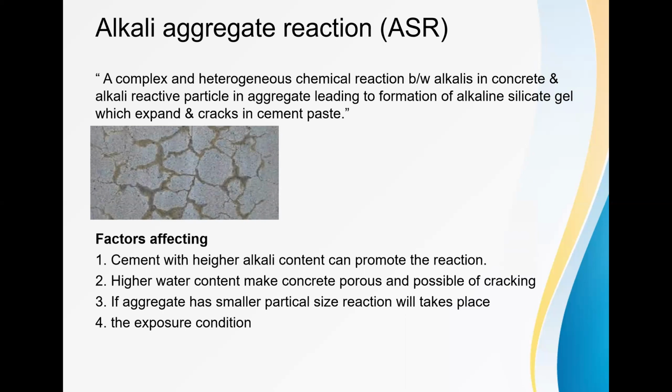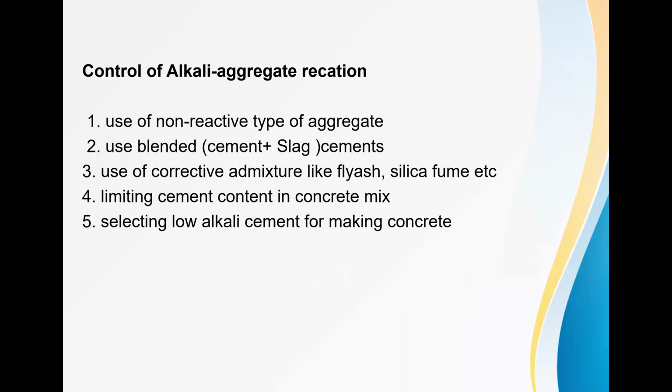Then what are the factors which are going to affect the alkali aggregate reaction? Cement with a higher alkali content can promote the reaction. Second, a higher water content makes concrete very porous and there is a possibility of cracking. Third, if aggregate has a smaller particle size, more reactions will take place. And fourth is the exposure condition.